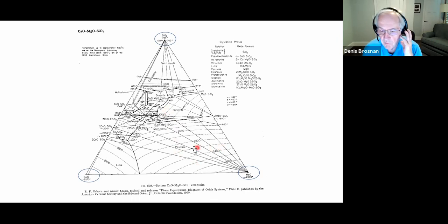And so we have little lines of constant temperature that are plotted on this phase diagram. We also have triangles that are compatibility triangles, and there are many of them on this diagram because this is a fairly complex diagram. We're going to reduce it. And these are compatibility triangles that tell you what is present for a composition at equilibrium if it's within one of these triangles.